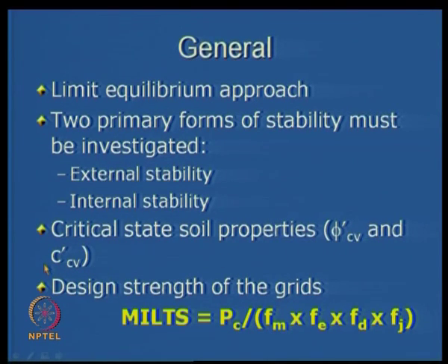These shear strength parameters should be obtained corresponding to large strains. This is what we saw in reinforced slopes also, that we conduct a direct shear test or a triaxial test. It is better to do a triaxial test in which you get c and phi as effective stress parameters, for 3 or 4 normal stresses, and then you get c and phi from these large strains.